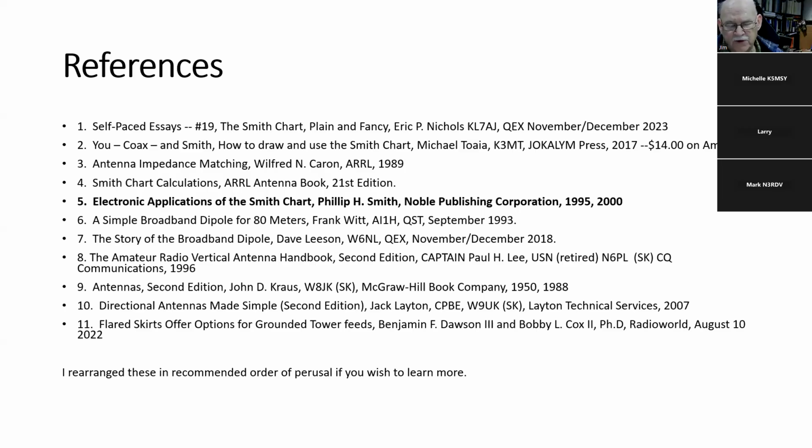He's got some information in there, and there are some other references that talk about radials. I've read a whole bunch of research on radials. It would be the subject of a separate discussion. But the bottom line is the more radials you have, the less anything else matters. How many, how long, whether or not they're resonant, whether or not they're on the ground, in the ground, or elevated. The more radials you have, the less anything else matters.